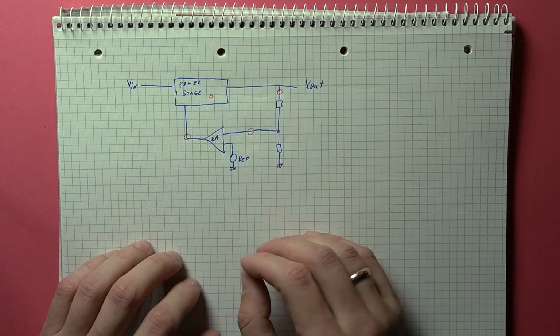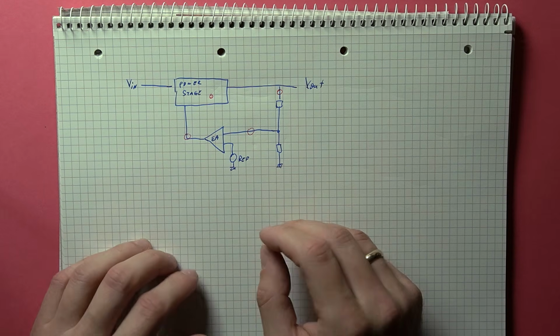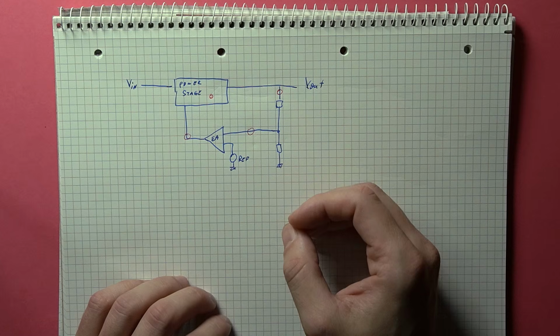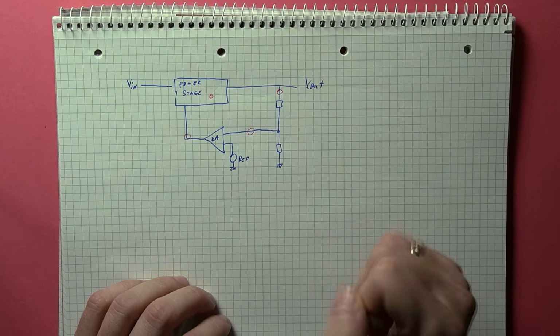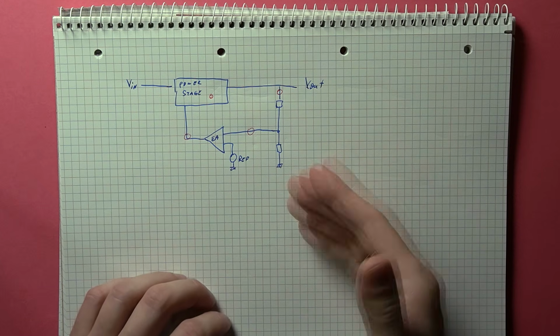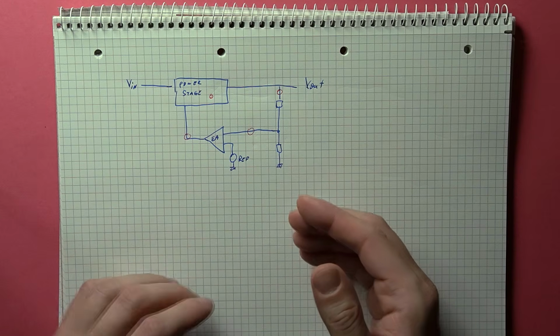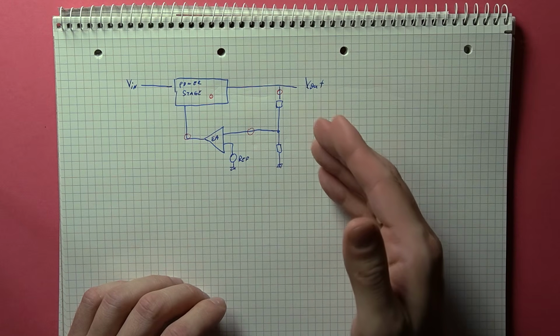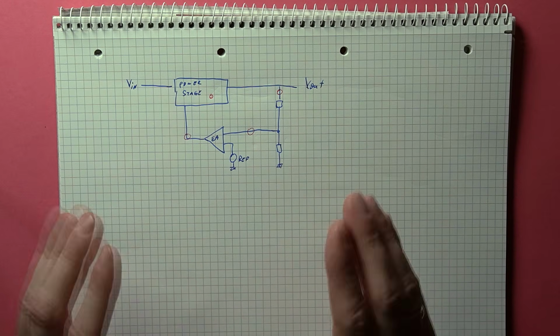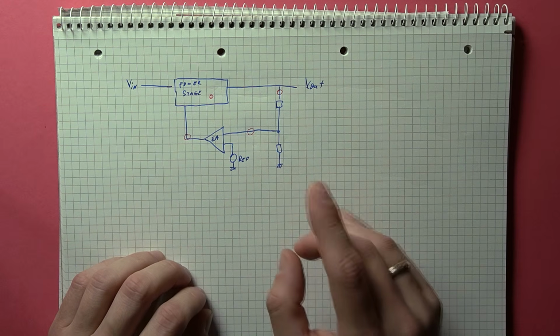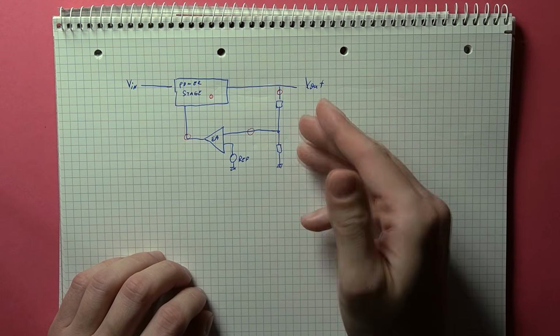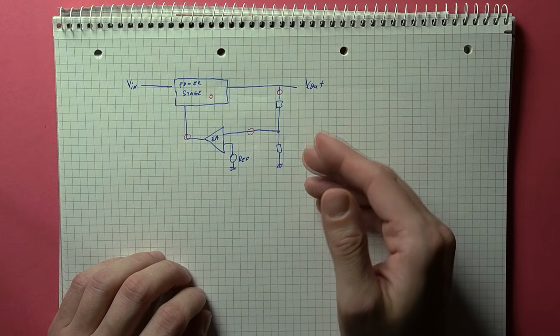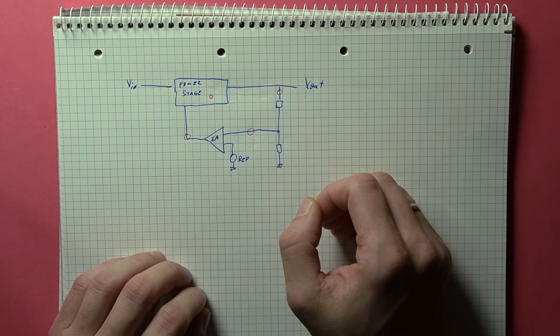So it's recommended that one side of the break is in a low impedance node, like the power supply's output. Since we are adding the small value resistor, this low impedance point is kept when connecting to the rest of the circuit. So the most common interruption point is above the upper feedback resistor, which connects to the output capacitors.